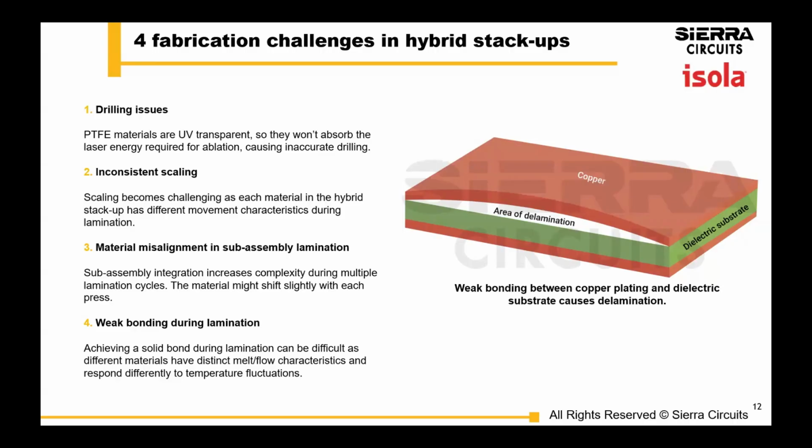And a hybrid stack up is very unique to your requirement. So most fabricators wouldn't have pre-existing data on the scaling for a hybrid stack up. So that's why a first article needs to be run.